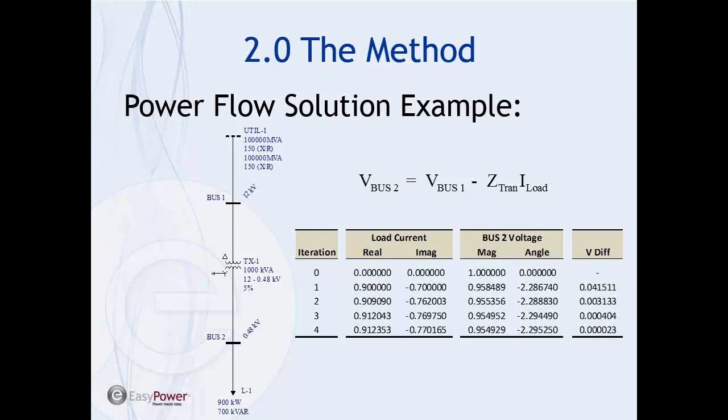And the reason why is because we're desiring to hold constant megawatts and megavars. Believe it or not, that's a non-linear solution. It's not linear. And so because it's non-linear, we have to iterate. Because every time we update the voltage based on whatever these conditions are, we see that the voltage changes.